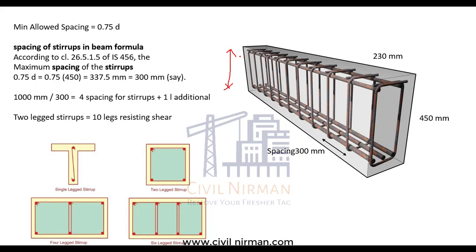And if this shear capacity is less than the actual shear force value, then we need to provide stirrups. The percentage of steel that we provide, that PT, will contribute towards your shear capacity. So based on the provided steel, it has some capacity to resist your shear force. Based on the required PT we provide some amount of steel. If the shear capacity of the section is greater than the actual shear force, then we don't require stirrups, okay?